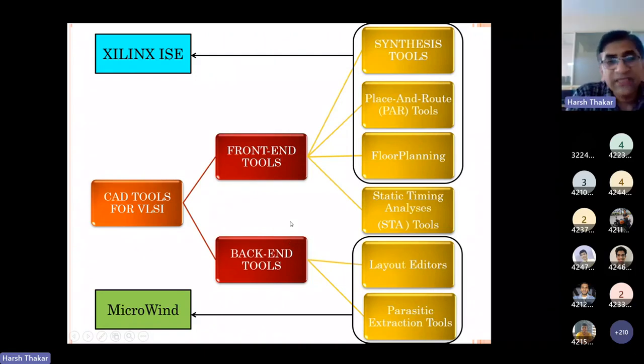If you remember my yesterday's presentation, journey from design to IC, in one particular slide I had shown that GDS2 file. So GDS2 file is actually the file which is sent to the fab lab for actually fabricating the IC. So if some of you must have made a PCB, to the PCB manufacturing vendor, we give what is called a Gerber file, right? So Gerber file is given to the PCB manufacturer, and based on a Gerber file, he will actually make the PCB for us. Similarly, fab labs expect us to provide GDS2, and Cadence is one tool, which is a backend tool which generates GDS2 file for us.